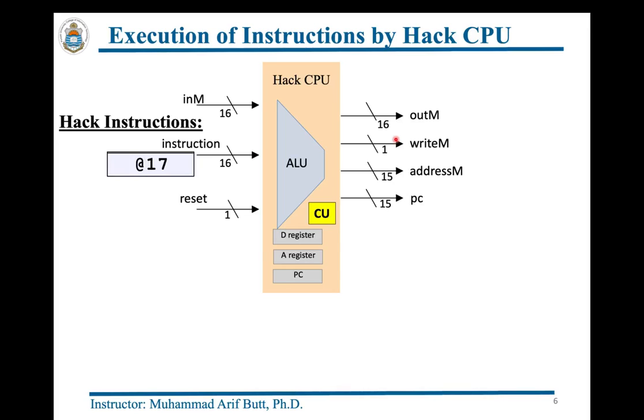Let's see another instruction, @17. Well, the value 17 is stored in the A register, and this value is also emitted by the 15-bit addressM output over here. This is what @17 will do.